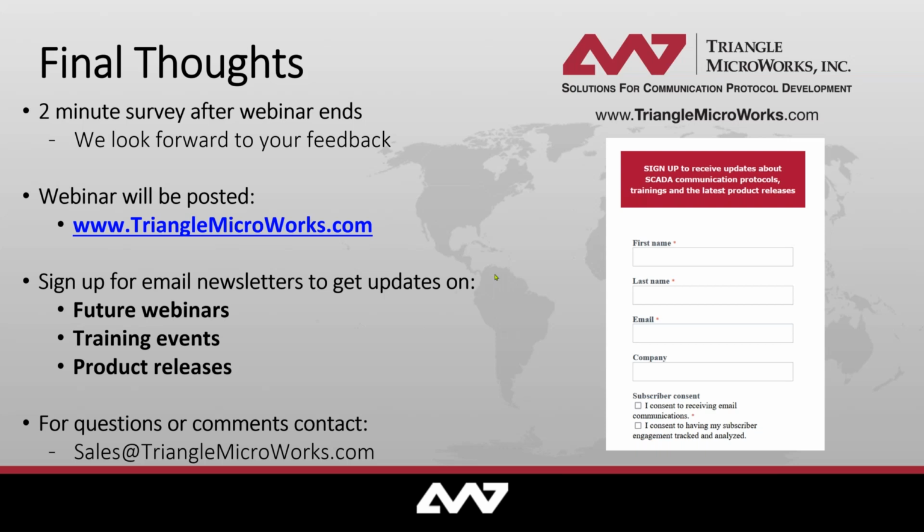Typically, when we have existing systems, you have the DNP3 communication to the substations, or maybe 60870-5-101. So when you introduce IEC 61850 in your substation, that does not mean that you now change the SCADA communication up to your control center. Applying a mapping, a gateway that maps between the traditional SCADA protocols and IEC 61850, is very common.